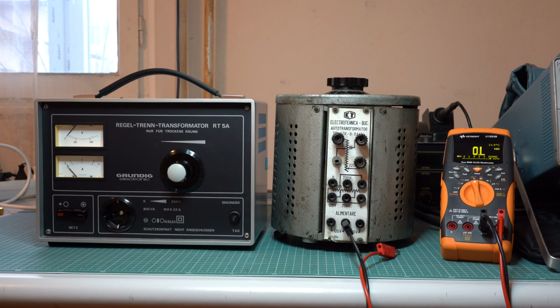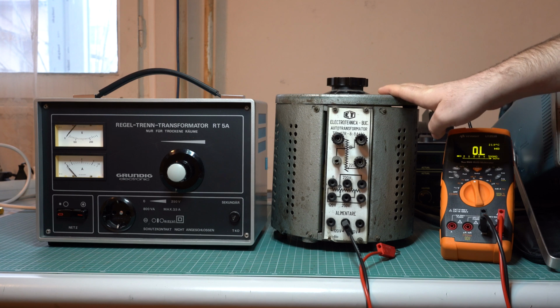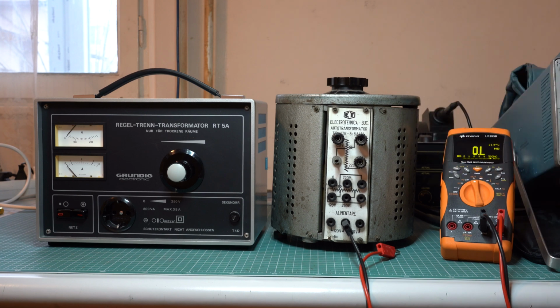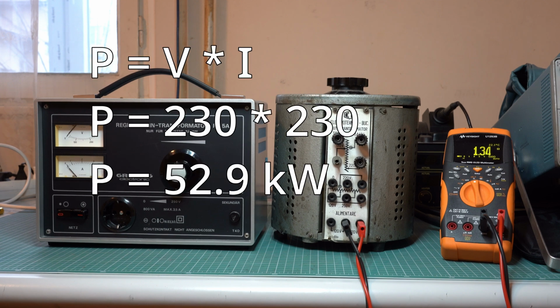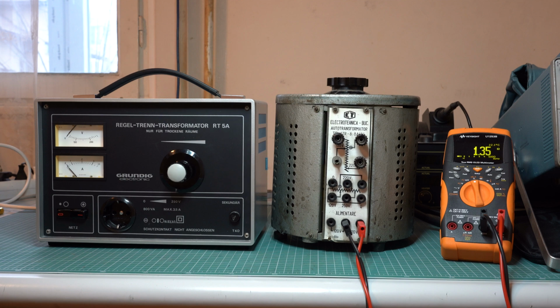Unfortunately, things are a little bit more complicated with AC circuits. For example, I have here this variac which will run at 230 volts. But before doing this, let's test its resistance to see what we get. Its resistance is a little bit more than 1 ohm, so let's do some simple math here. Let's assume that this variac has a resistance of 1 ohm. So by plugging it in at 230 volts, we should get a current of around 230 amps, which gives us a power of around 53 kilowatts. So basically it will look like a dead short. Let's see if that's the case.